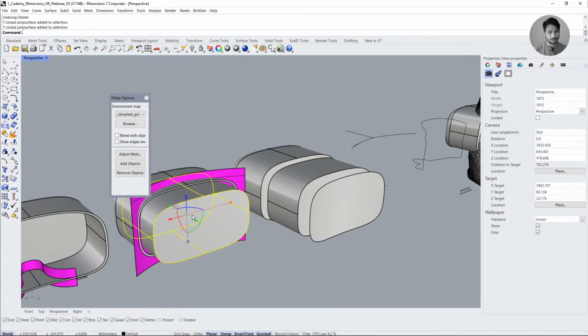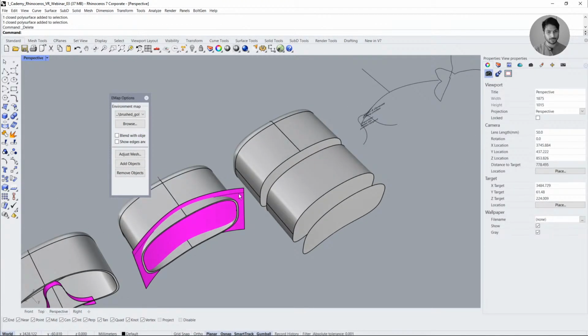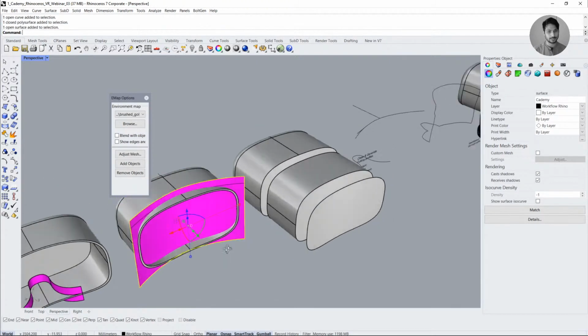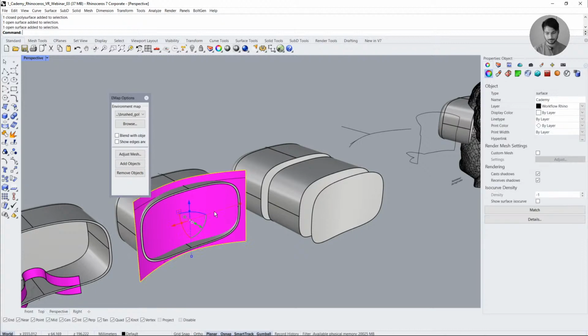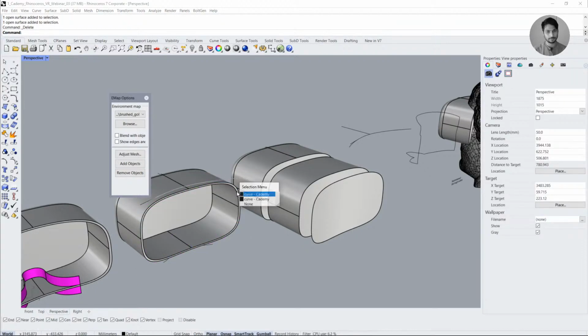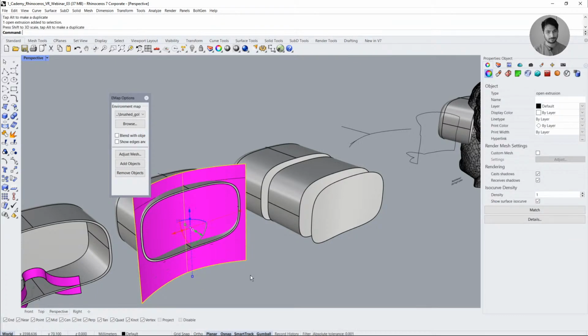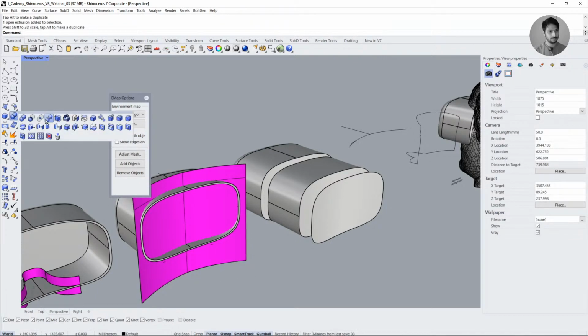And once you have the hollow structure, you can use this curve that you have here to split this geometry with that plane. Okay, have that curve, just extrude it, and we will do Boolean split or Boolean difference.